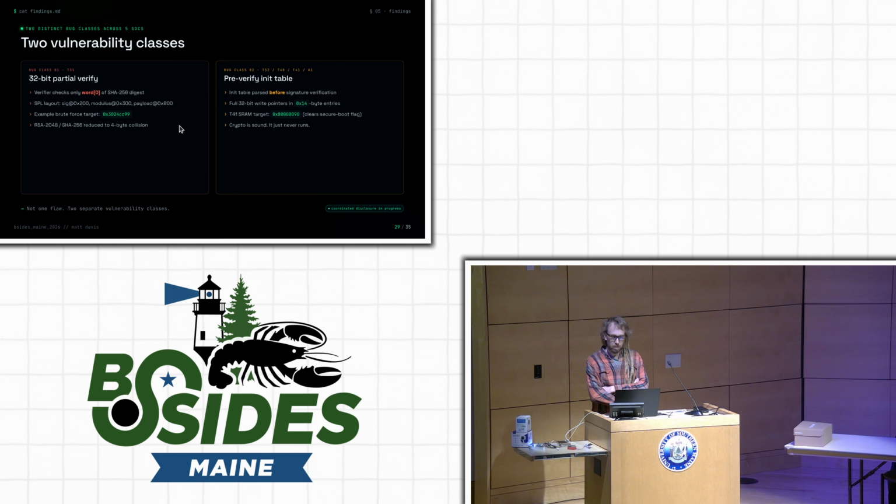We wrote a simple Python script that patched the exact bit or byte of the firmware, and it basically reads the fuses, says secure boot's on, the bootloader runs a little bit more, encounters an instruction, says secure boot's off, and then it boots whatever you want. Cool.